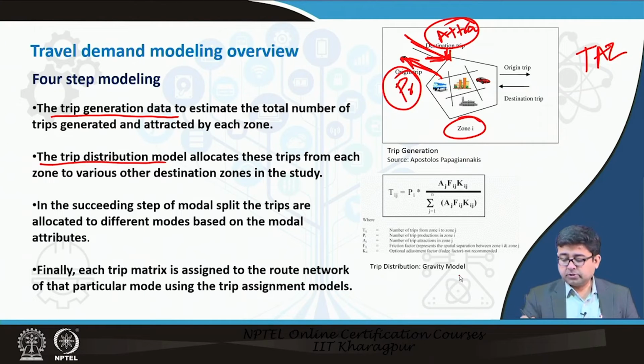Usually the most common model that it develops is the gravity model. It says that trips between two zones are directly dependent upon the attractions that are available in the other zone and the distance or travel time between those two. So, if there are a lot of attractions in a zone, it is likely that a trip that is produced in one zone is being attracted to that zone. An attraction could be a movie theater, a park, a restaurant, or a number of restaurants.